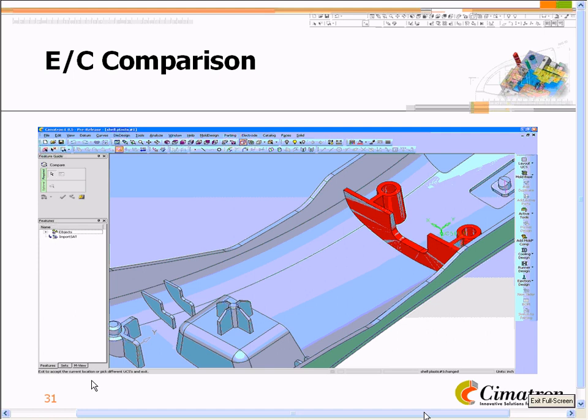If I bring it right into the part with the new data, that immediately updates all my drawings and it flags everybody and then sees that the data's changed. From there, I may make a few decisions. Does it affect parting line? Do I need to move an ejector pin? Do I need to move a water line?